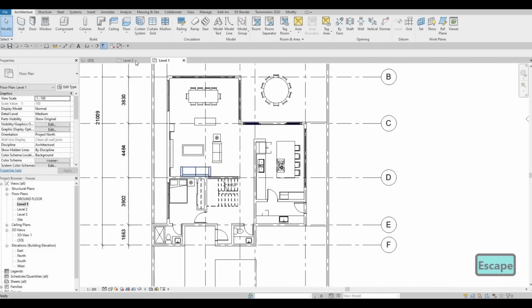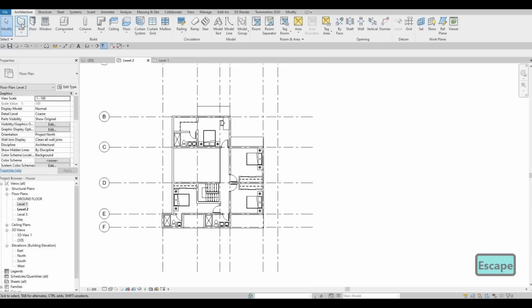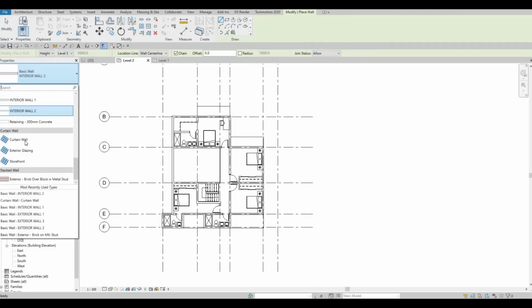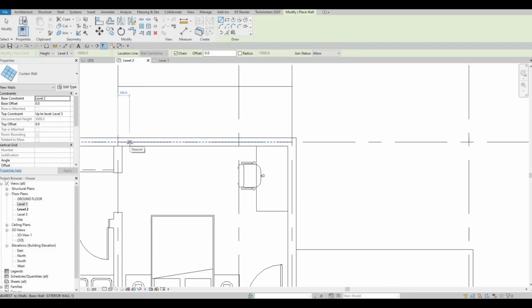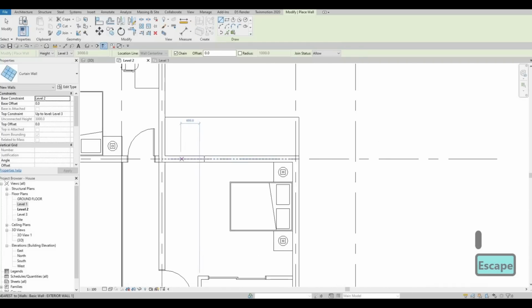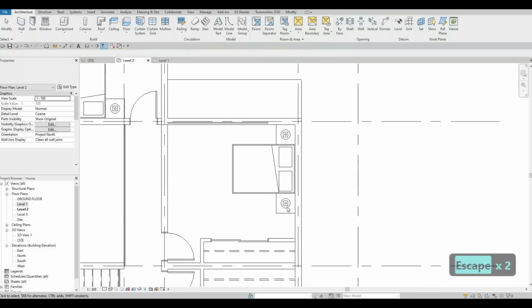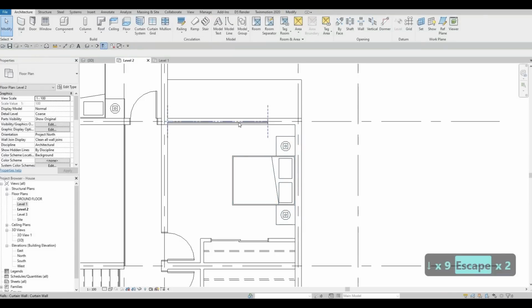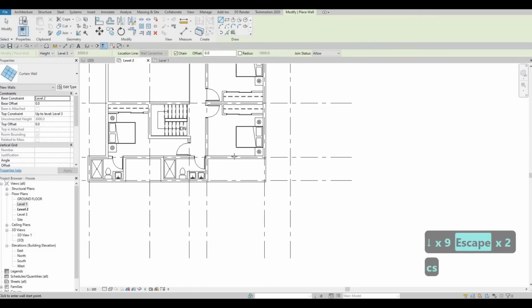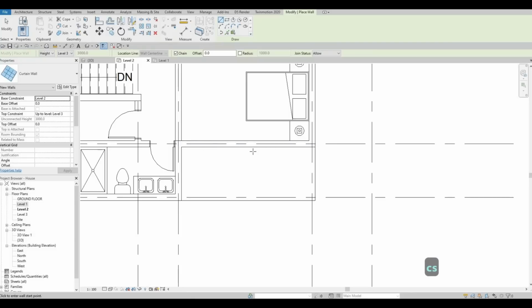So let's add in the curtain wall first. So click here, drop down curtain wall, and then obviously we need to add curtain wall right here. Flip it like that, obviously right here as well. Flip it like that, and then here we could just move this one right about here because we have enough room. CS, let's add it right here,